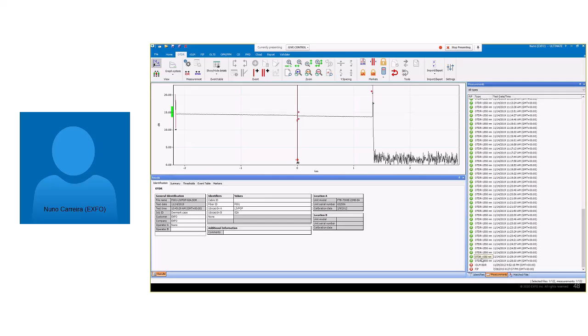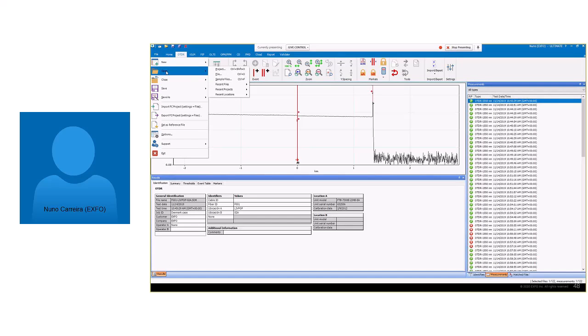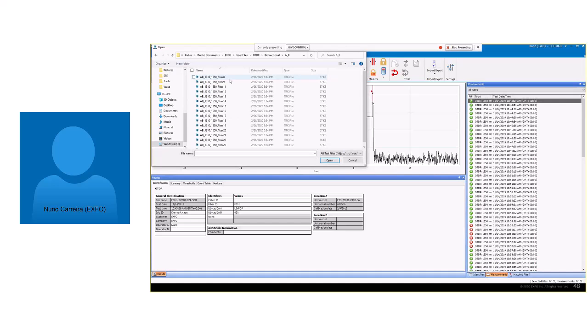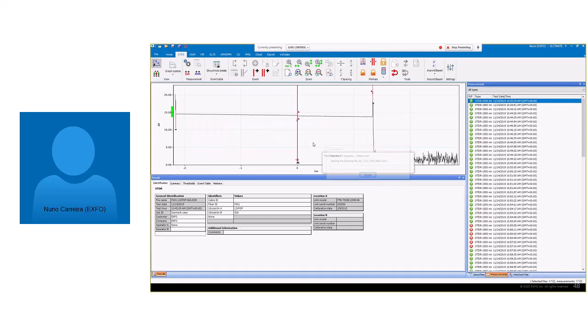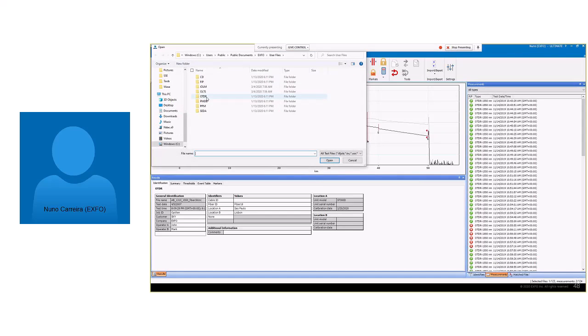Apart from this simple modification, if I want to go for the bidirectional, if some of you also do bidirectional, I can open an OTDR example of a bidirectional, which is normally interesting to see how quick. So I will open here an example with fiber 18, A to B, and I will replicate, and I will open a sample file for the OTDR as well, bidirectional B to A.